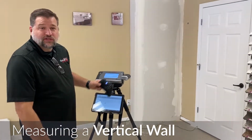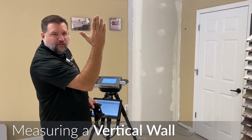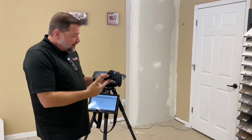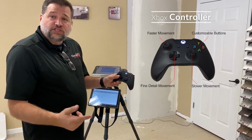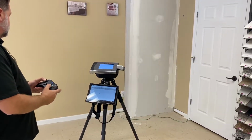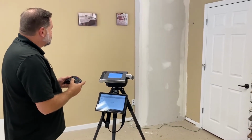All right, guys, now we're going to measure this vertical surface. We're going to call this wall 1. Same thing as measuring a countertop. You can imagine we just turn it on a vertical plane. Pretty simple process. In this application I'm actually going to use the remote. The remote has buttons A, X, Y, and B that are programmed to what you need them to be. A happens to be multiple lines. So why don't we do this? I'll come down. Because we already have a plane, we're able to project this.